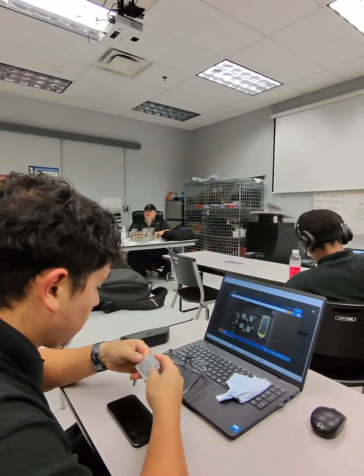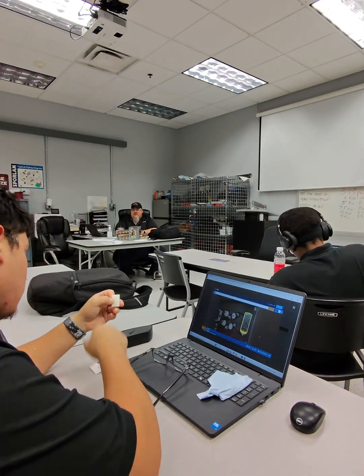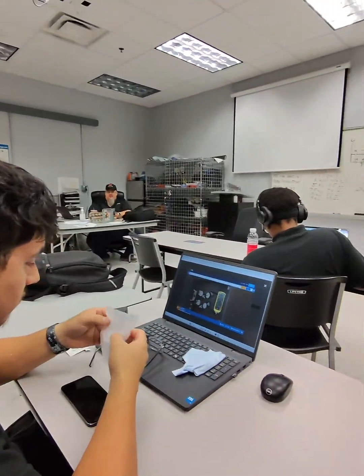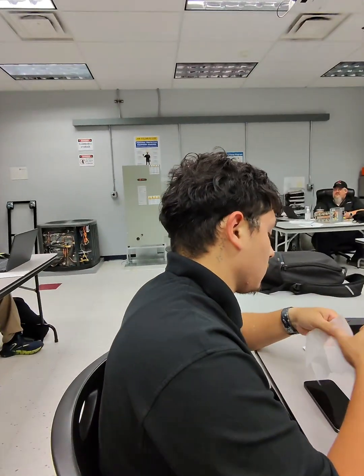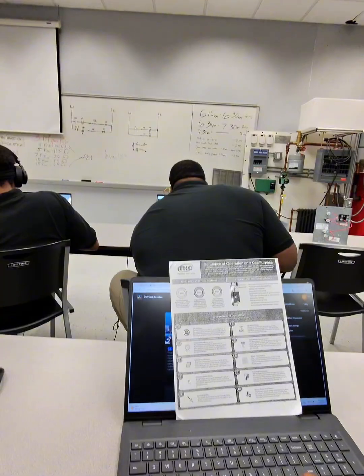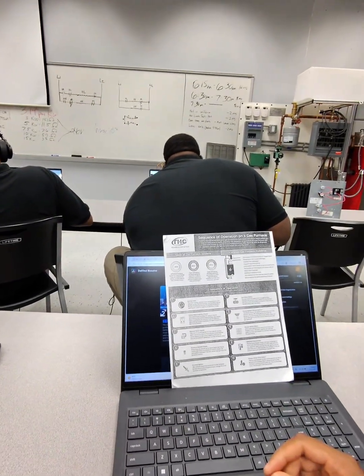Not the gas valve. Something happens that has to happen before gas comes on. The furnace igniter. Igniter comes on. Alright, what comes on after the igniter? The gas valve opens. The gas valve opens. Burners. Flames on. Then what happens then?